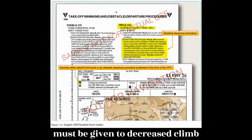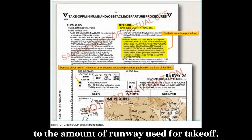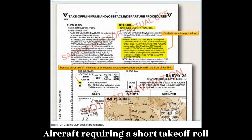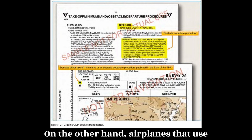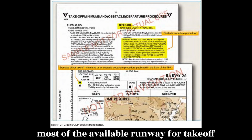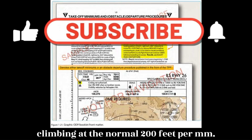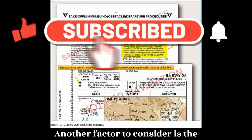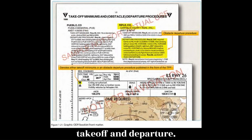Consideration must be given to decreased climb performance from an inoperative engine or to the amount of runway used for takeoff. Aircraft requiring a short takeoff roll on a long runway may have little concern. On the other hand, airplanes that use most of the available runway for takeoff may not have the standard ROC when climbing at the normal 200 feet per nm. Another factor to consider is the possibility of an engine failure during takeoff and departure.